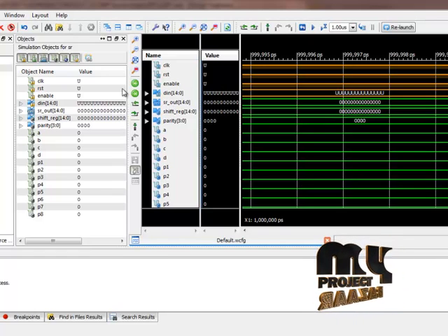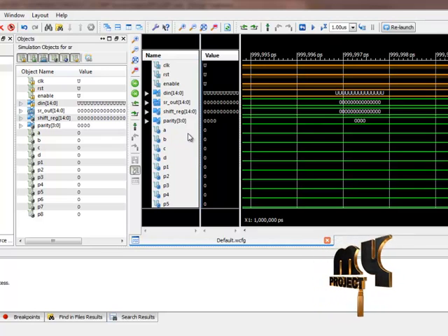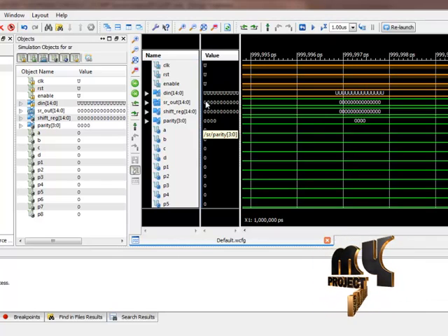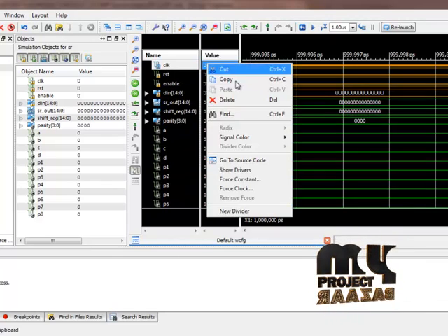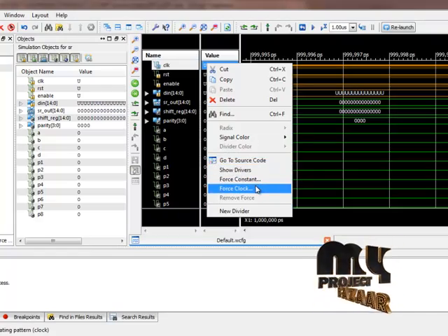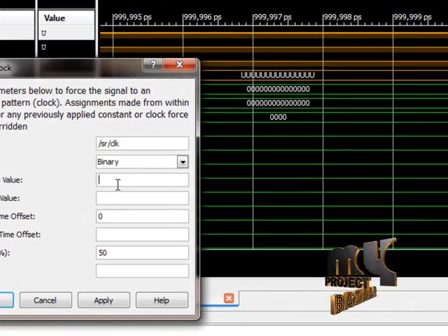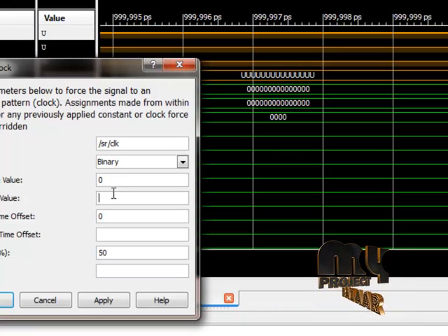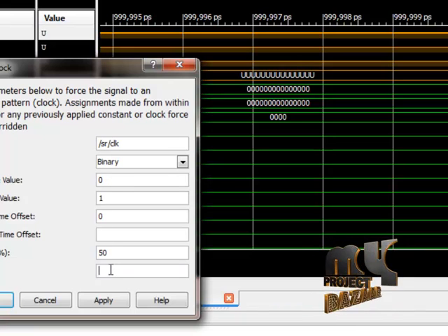The SR output gives the result after the shift register, and we are checking the parity level for the LDPC code. Now we are checking the process for the clock. So give the force clock: leading edge value 0, trailing edge value 1, period 1000 ns.